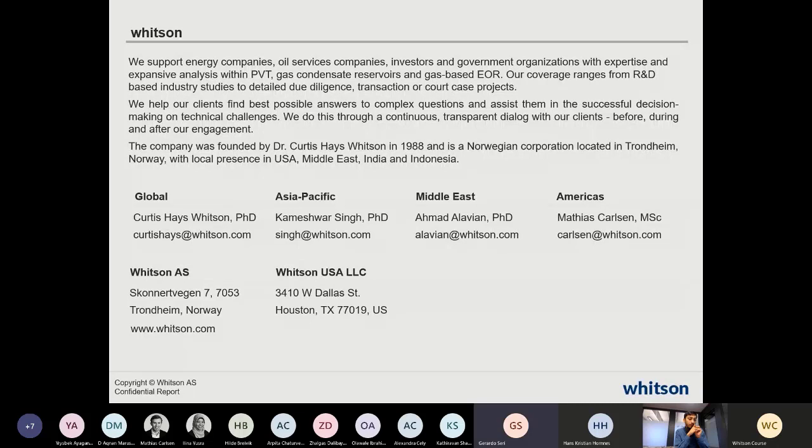Is there at least, yeah, because I noticed that when we are trying to define the gas-oil contact by equation of state, right? That's a typical exercise. Now, is it something that says, okay, but if you are in less volatile fluids, it might improve compared to volatile fluids? No, I don't think there is any literature or any paper on this that if you have such kind of fluid system, you should be using the fluid gradient calculation with thermal gradient.